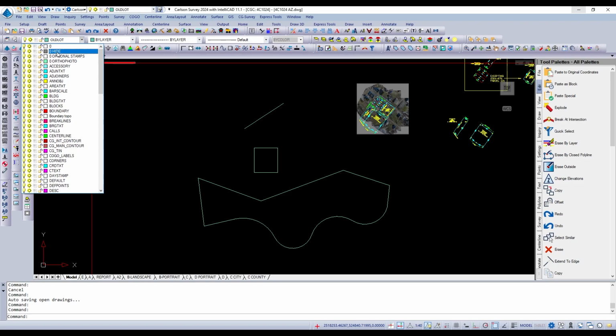This 0 hide. These are entities that I want to hide from the drawing, not plot, not include in the current data that we're using and things. D plots, things like that, sometimes I'll put there just to get them out of sight and not plot them, but I want to save them for later for some reason.